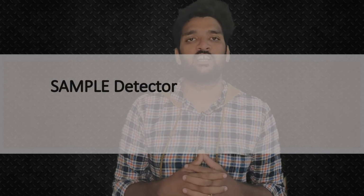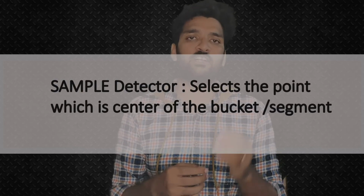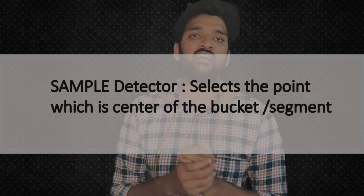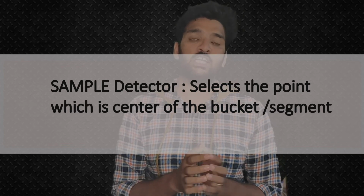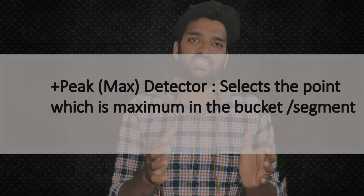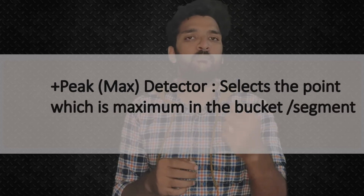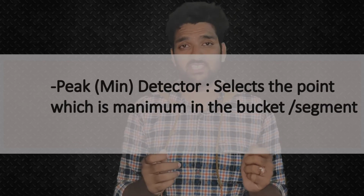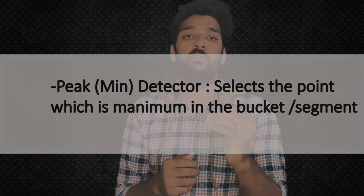For example, if you choose sample, it takes the point which is exactly at the center of a segment. If you choose the max detector, of all the points in a segment, the max value would be picked. If it is min, of all the points in a segment, the minimum value would be picked.